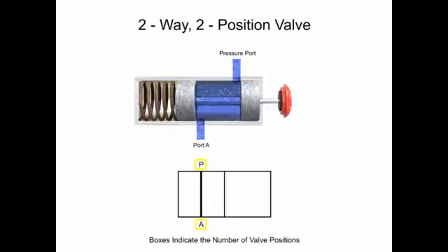For complex valves, the ports may also be labeled. The input port is typically labeled P for pressure. Outlet ports are typically given alpha characters starting with A. Other times, the letter stands for the destination of the fluid. For instance, the letter T would indicate a port that is connected to a tank. This is a fairly simple valve, so port labels are not required.